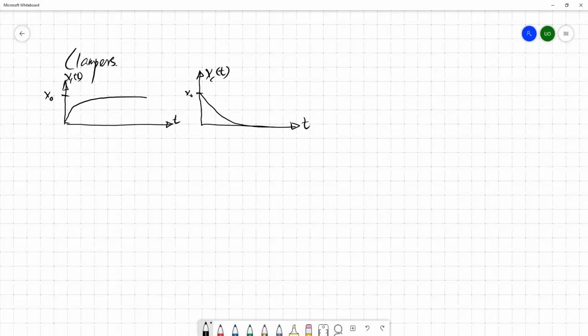So then we found that once you apply this external voltage, this capacitor gets charged up to V naught, and it will take a certain amount of time to charge to maximum. Similarly, once you charge the capacitor and connect it to a resistive load, the stored energy is released or discharged through the resistive load. So this is the discharging process of the capacitor, and this is the charging process.